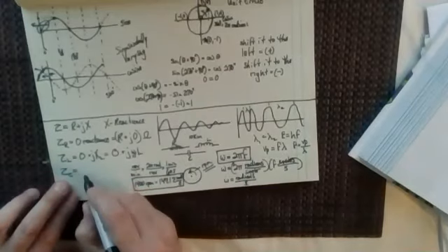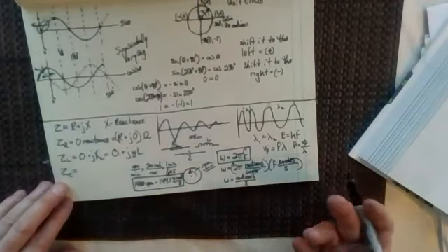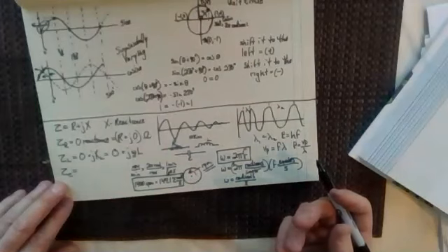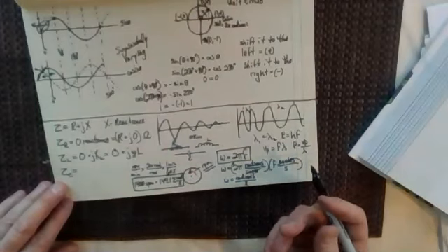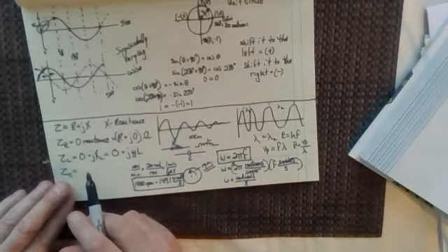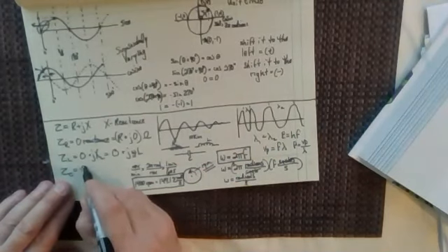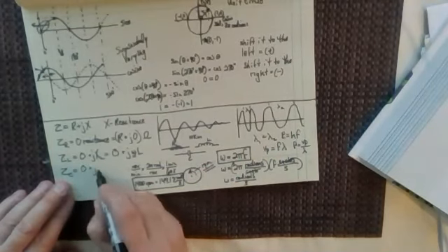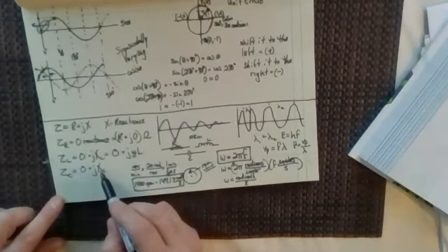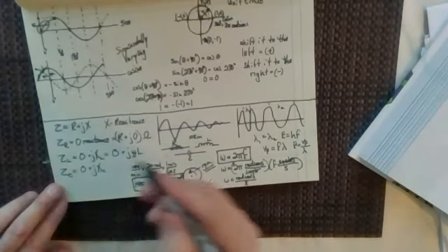I've got capacitance, and a pure capacitor is actually much closer to reality than the inductor, because the inductor has huge windings of thin wires, so that's obviously going to cause some resistance, isn't it? Whereas the capacitor is really just two plates separated by a dielectric, and that makes this much closer to reality. And so this is 0 plus j x sub c. But this is where I teach this differently than other people teach this.